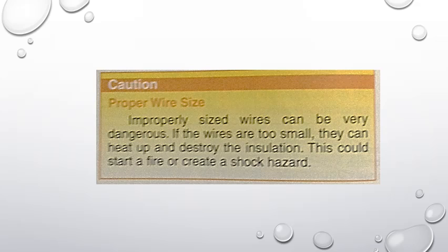Conductor size. The size of the conductor to be used depends on the amount of electricity that it must conduct, the length of the conductor, and the type of environment in which the conductor will be used. Our discussion of wire sizes is limited to copper wire. For aluminum, a wire size larger than that of copper is always required. Refer to the NEC to determine the correct size.